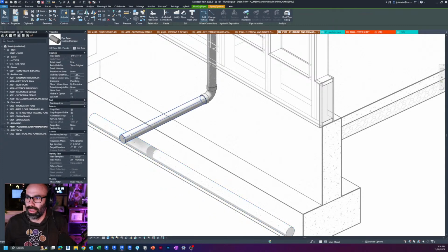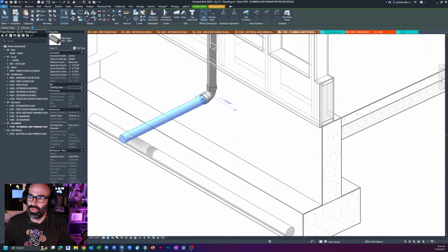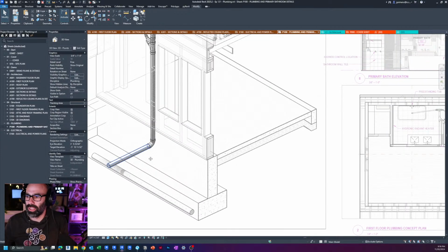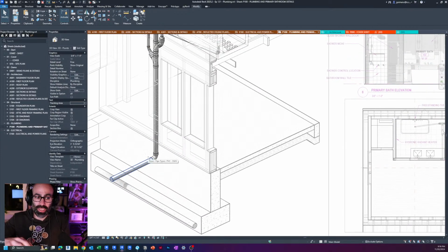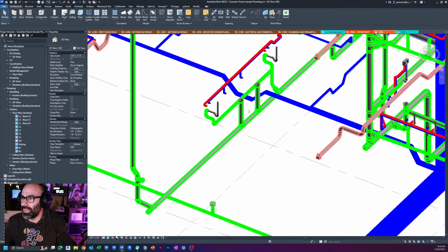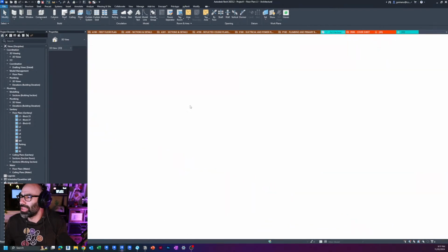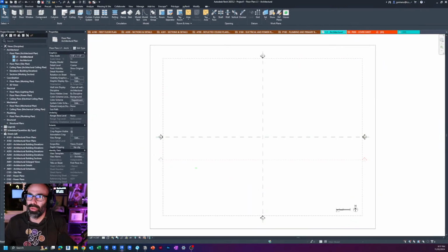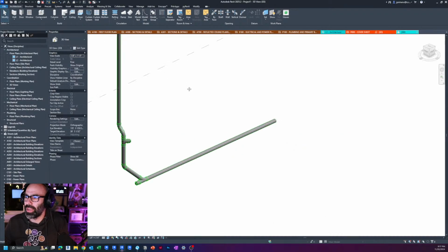And so even for this guy, for example, this one you could see here, I made a system called footing drains and a type, right? And then for this one, it's just PVC piping. It's all basically drainage stuff like that. So I utilized that. I literally just copied that in, and then I was able to start. And what happens when you copy that in is that it brings in those routing preferences and those system types. Okay, using the out-of-the-box multidisciplinary probably wasn't a good idea because I already had them built in. But that's okay. And so I'm actually going to go in 3D.